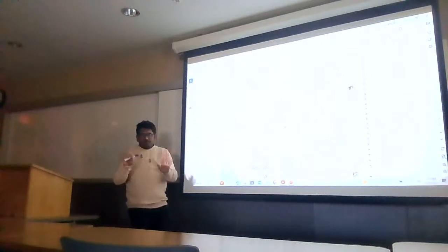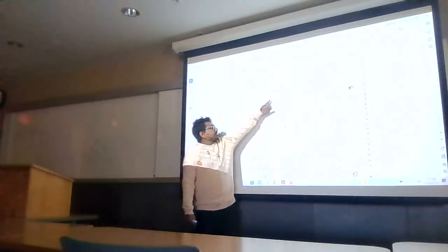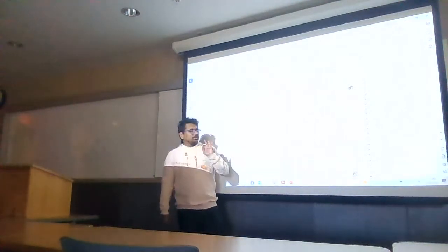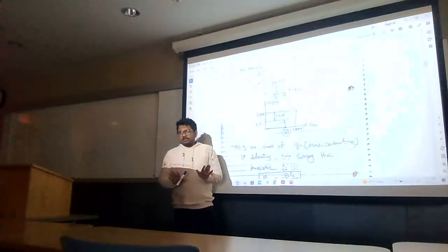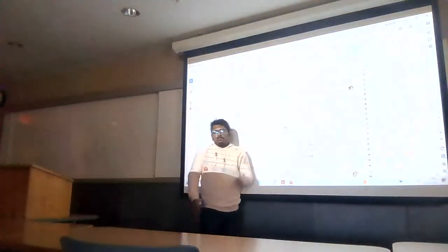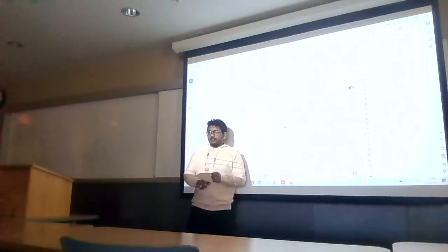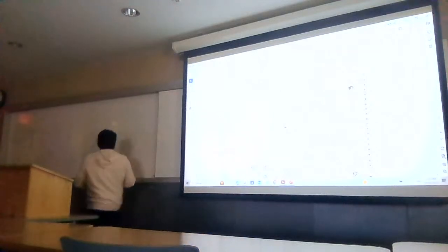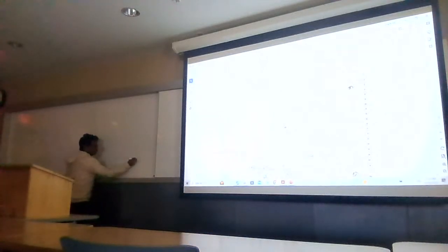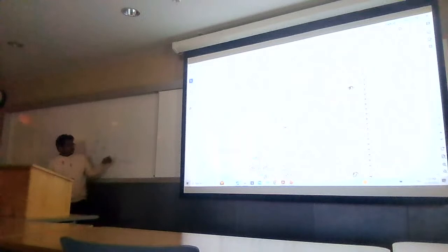Now let's say you can assume that at 750 millivolt, my transistor reaches saturation. But now you have to consider whether you are okay with 750 millivolt or not. I'm drawing here. Let's say this is my saturation curve, and I find that this is 750 millivolt, and it is guaranteed that whenever I apply 750 millivolt or greater, my transistor is in saturation. I'm okay. But